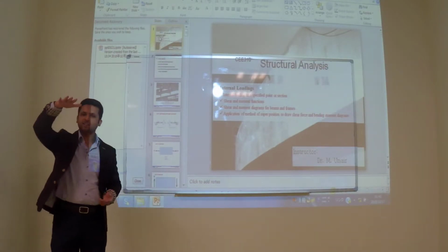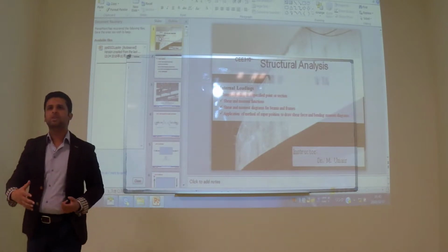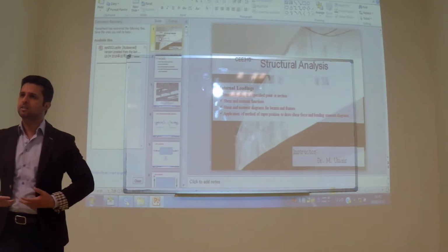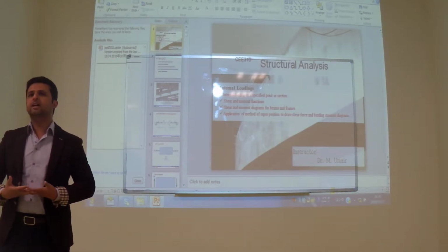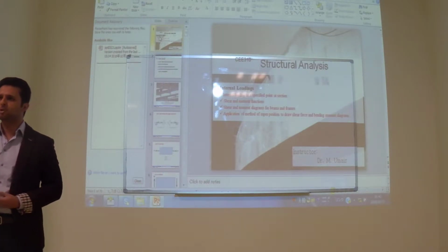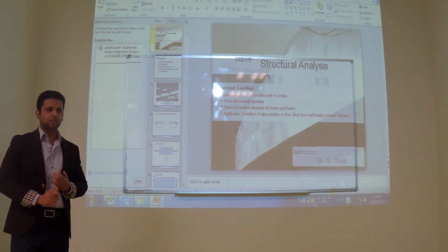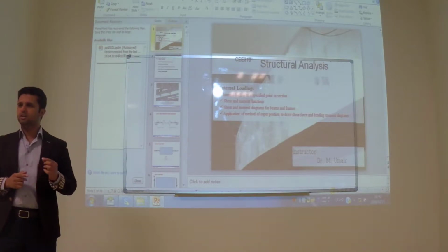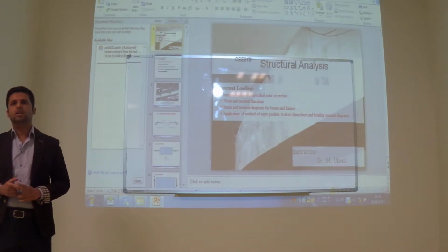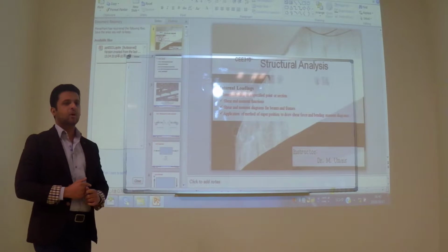Once you apply any force on a beam, the beam gets internal resistance, and that internal resistance causes internal forces. There are three types of internal forces: normal force, shear force, and bending moment. There is torsion, but that is out of the subject.